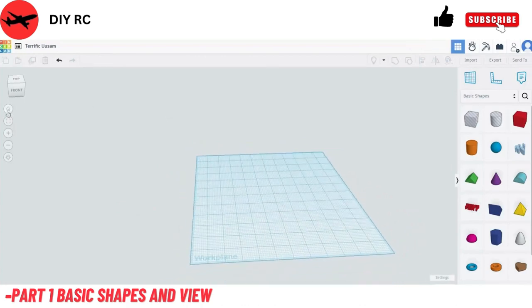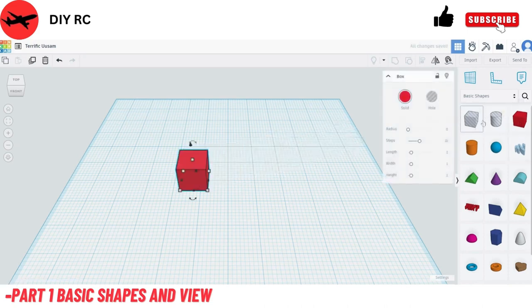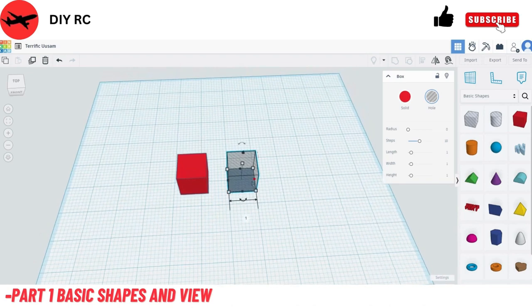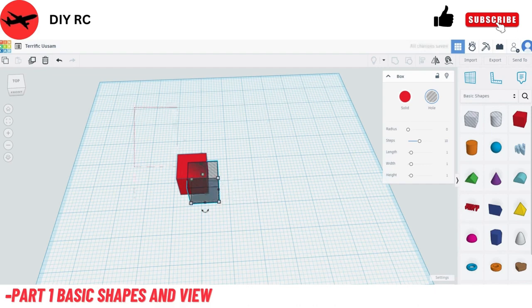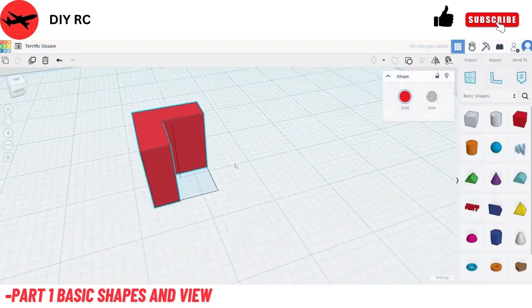And now we're going to talk about how we model in Tinkercad. So there's two shapes that we can model with. We have the solid block, and then we have the hole block. And then there's different shapes for whatever you need to be doing. Now, if we drag the hole block so it's overlapping the solid block, and then we left click and combine them by pressing this button, or we can do Control G, and that will take a chunk out of the solid block.